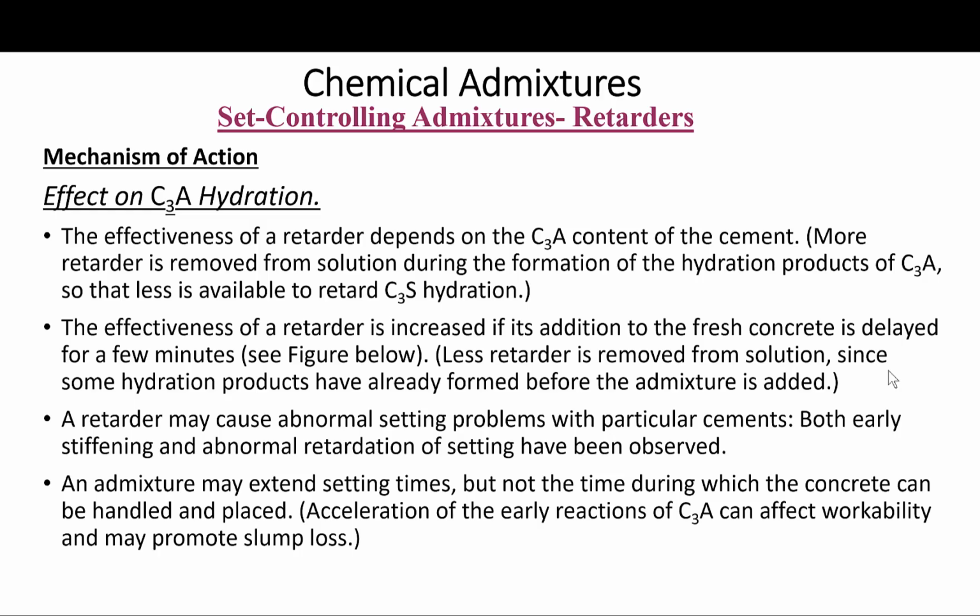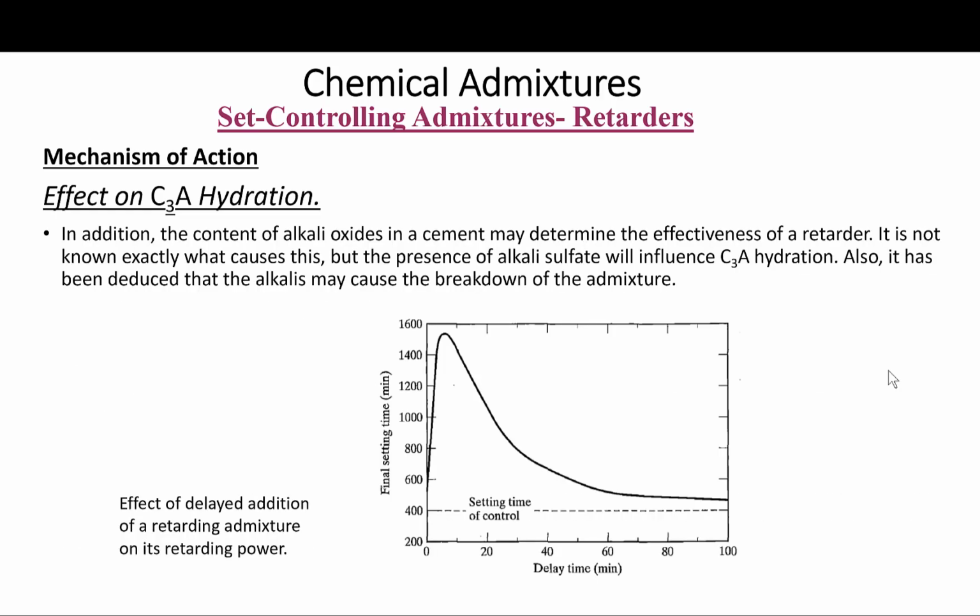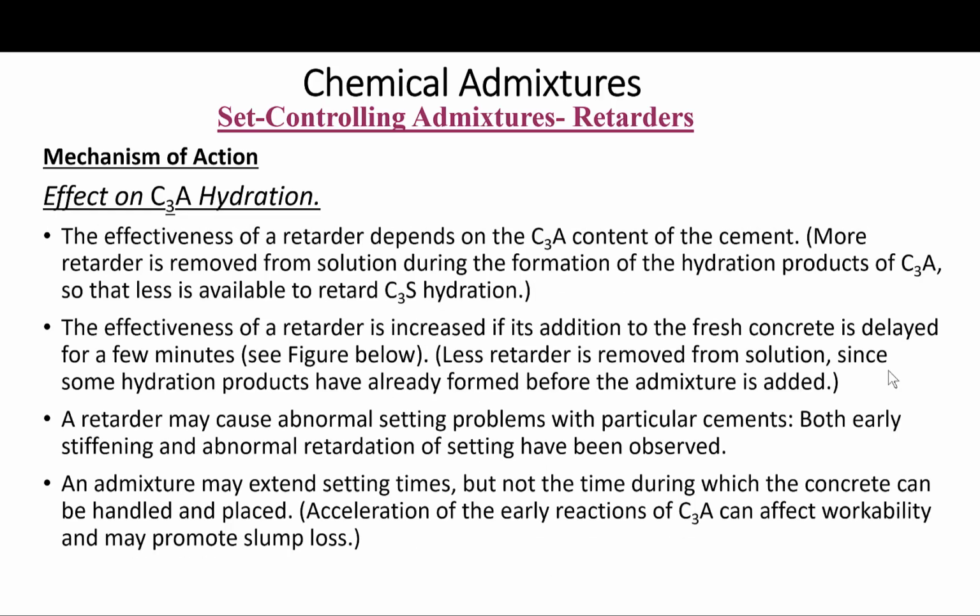Second, the effectiveness of a retarder is increased if its addition to the fresh concrete is delayed for a few minutes, as you will see here in this figure. I'll talk about it in a minute. Okay, so less retarder is removed from the solution since some hydration products have already formed before the admixture is added. Okay, in the case of the delay.